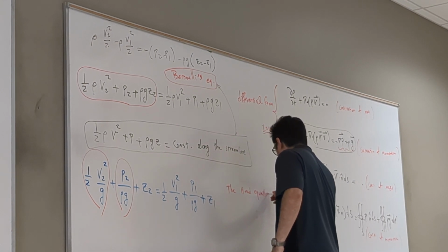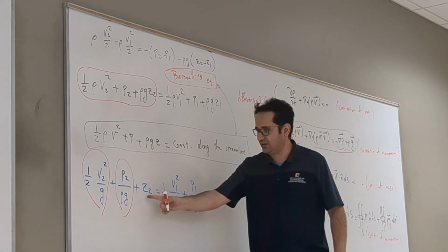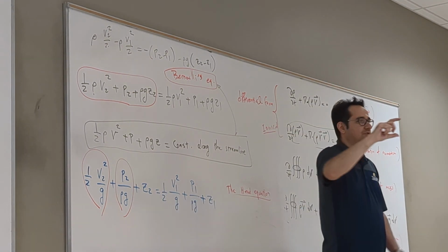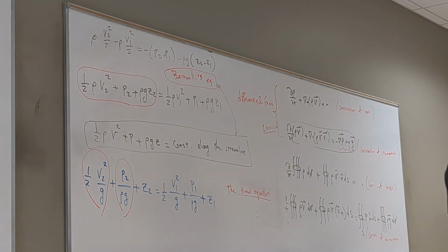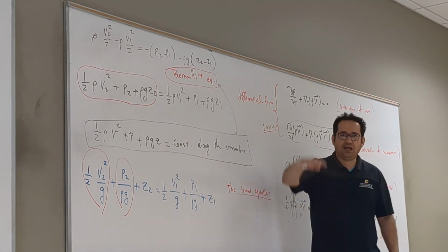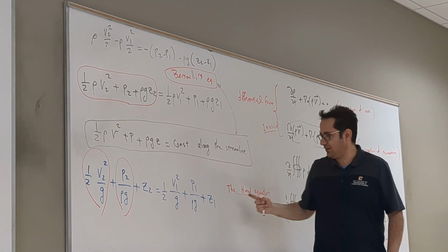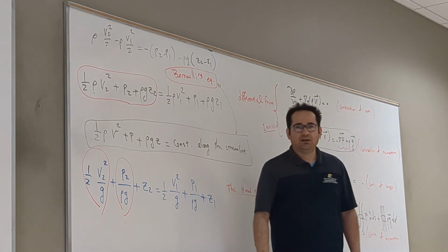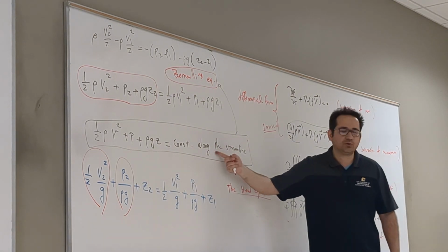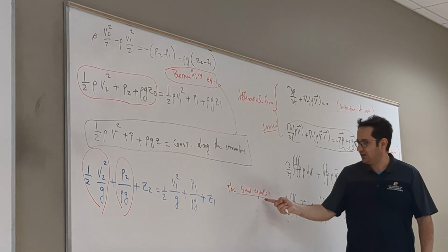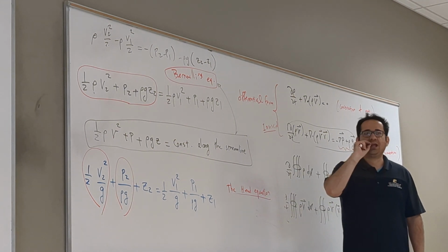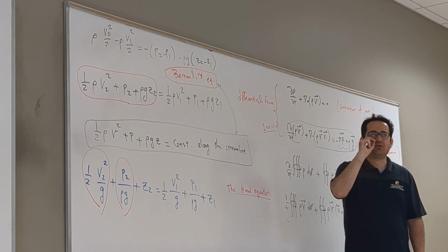Why? Because you see that this is the height that you see in the tube, the actual tube that you measure. We're going to solve a problem. So this is the amount the head goes up or down, and that is proportional to this sum. And another representation of Bernoulli's equation, in just one sentence: the head is constant along the streamline.